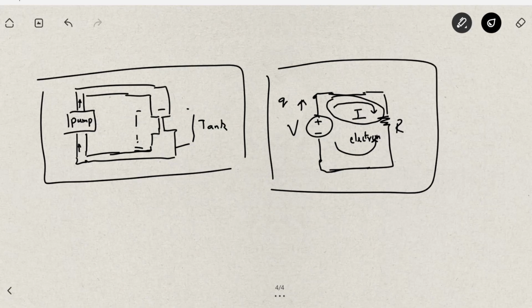In a similar manner, just like a pump is pumping water into the tank and getting water back from the tank, there's a continuous flow of water. Similarly, as long as this voltage source is connected to this resistance, it will be driving electrons through this resistive circuit. Now why did I show this tank to be constricted here? If you have a very narrow tank, or a nozzle, whatever it is, the pump will have to do more work to pump water through this gap.